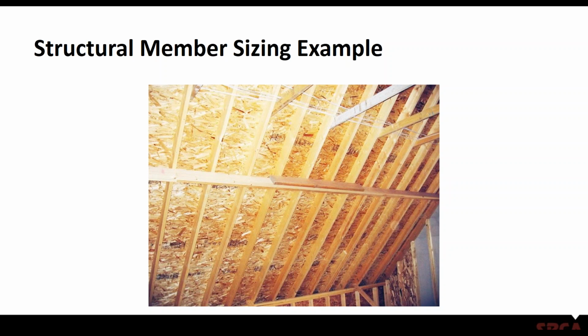But what's missing here, and probably is, these were not designed, you're missing some type of, you'd have to have either a rafter tie or a ceiling joist, which I don't believe is going to be installed in this particular application. Now, the only way really to get around this would be to design the ridge board as a beam. That beam is going to help carry half of the load and transfer the other half of that vertical load, gravity load, down to the walls. And by putting a beam in, you've taken a lot of the thrust, in fact, pretty much all of it out of the rafter. But in this case, they haven't done that.